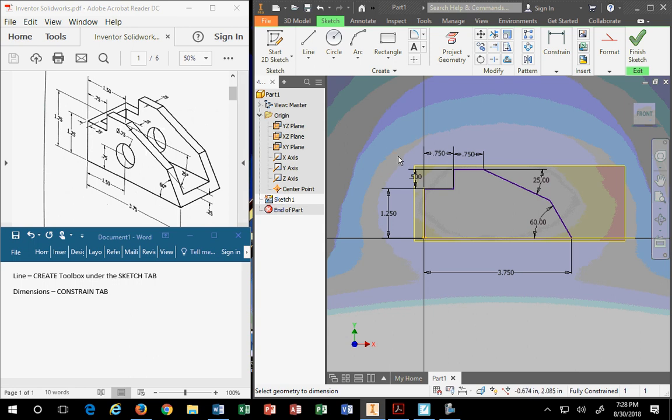1.625. Correct? If I assigned an 1/8 inch tolerance to these two, these are stacked dimensions, they're right next to each other. 0.75 with 1/8 of an inch is 0.875. 0.875 plus 0.875 equals what? 8 plus 8 is 16. 1.75. Is 1.75 tolerance acceptable if the customer really gave me a 1.5 inch dimension with a 1/8 tolerance? That means the max is 1 5/8.